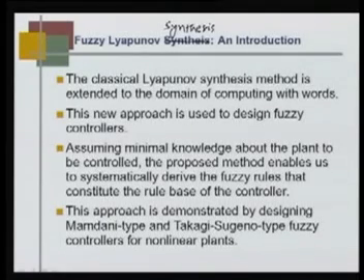Fuzzy Lyapunov synthesis: an introduction. The classical Lyapunov synthesis method is extended to the domain of computing with words. This new approach is used to design a fuzzy controller. Assuming minimal knowledge about the plant to be controlled, the proposed method enables us to systematically derive the fuzzy rules that constitute the rule base of the controller.